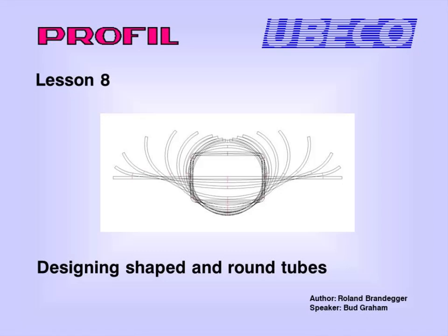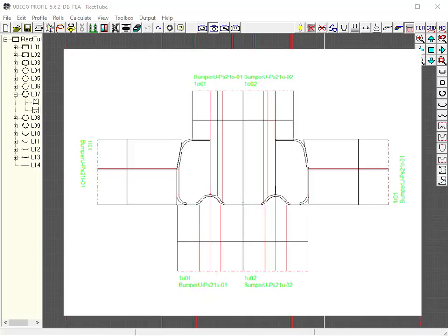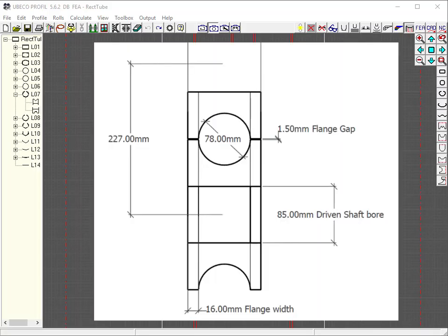In this lesson, we will design a set of roll tools to reshape a closed or welded tubular section. In our previous lessons, we defined open profiles where the upper and lower, and sometimes side rolls, need only create parallel paths between roll faces to bend metal to the desired shape. In welded tube production, we encounter a different set of processes where we are combining bending and compression of sections or the entire cross-section to create a new desired shape.